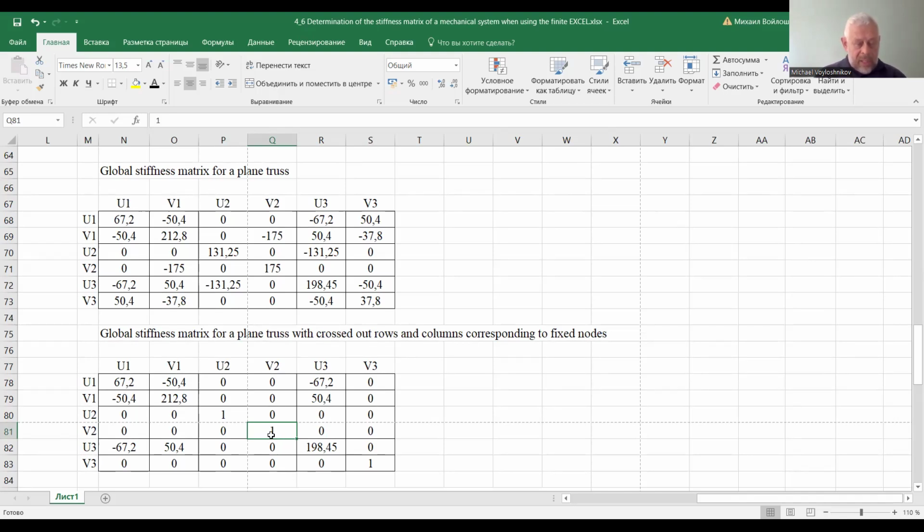This is a supported node. So we specified 1 into the matrix of stiffness, and all other elements of the same column and the row of this matrix corresponding to this definite cell of 1 have to be 0. And so very many zeros and only 2 ones.